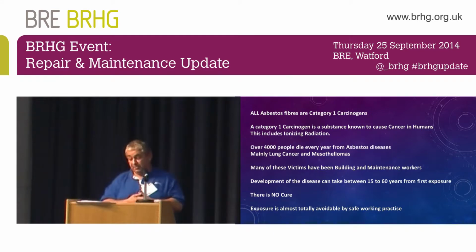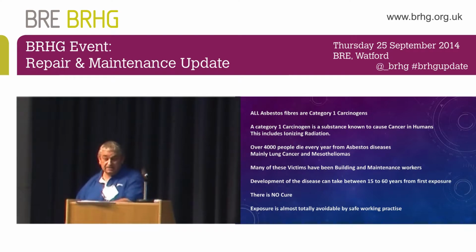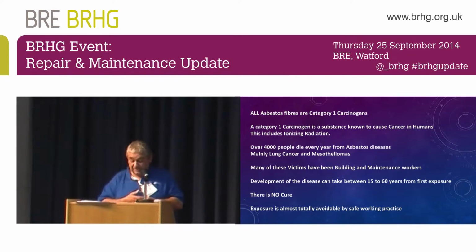And it's a similar problem we're going to get with crystalline silica, where you see the guys cutting up slabs and concrete and not using wet work, which instantly gets rid of the problem. They're all getting these massive exposures of crystalline silica, because there's quite a lot of crystalline silica in modern building materials. There's no cure. There's no cure to mesothelioma once it's diagnosed.